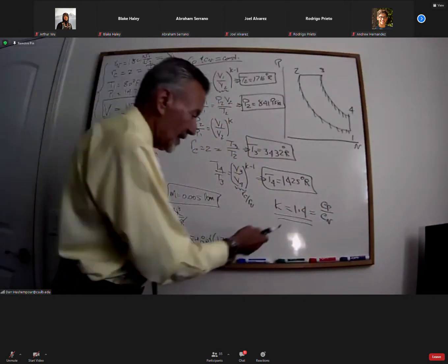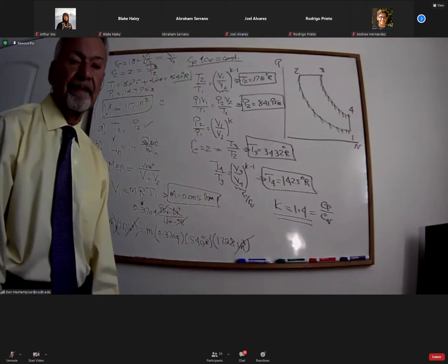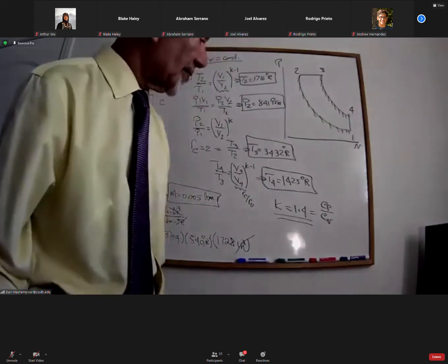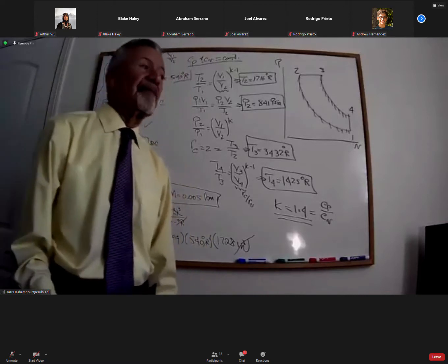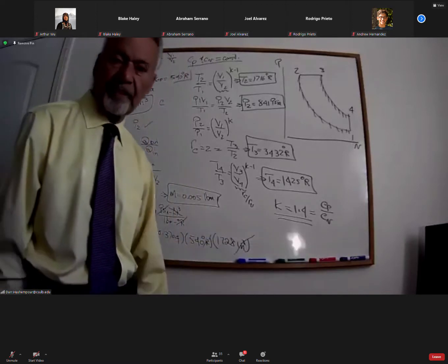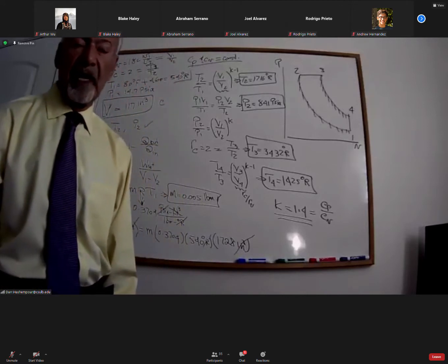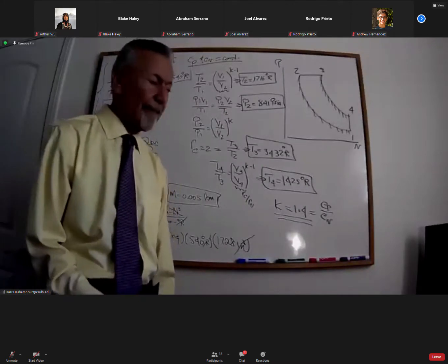And that's how we can find the value of K. Okay, thank you. No problem. Sometimes the problems say assume K is equal to 1.35. Then you have to just, instead of 1.4, put 1.35. But if nothing's said, K is 1.4 for air.